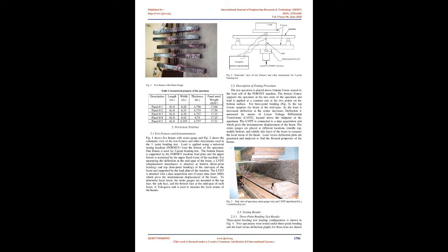The composite sandwich beams were made of E-glass fiber and polyester resins, and the core consisted of corrugated cells in a sinusoidal configuration. Based on the modeling of equivalent properties for the face laminates and core elements, analytical predictions of effective flexural and transverse shear stiffness properties of sandwich beams along the longitudinal and transverse to the sinusoidal core wave directions are first obtained. Using piezoelectric sensors, the dynamic response data are collected, and the dynamic characteristics of the sandwich structures are analyzed, from which the flexural and transverse shear stiffness properties are deduced.